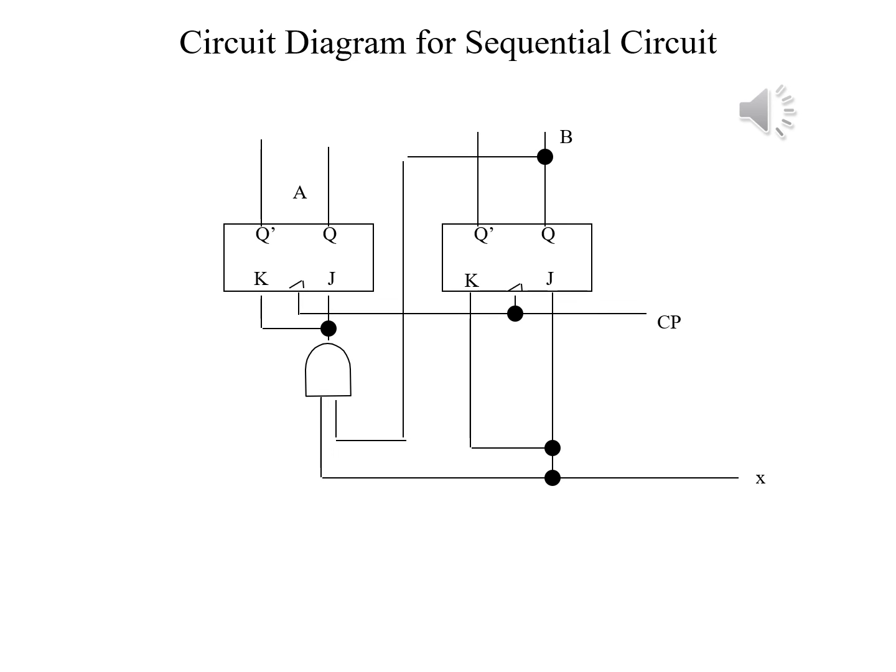Here we see the final circuit. X goes into J, but before that happens, it splits off twice. One to go into an AND gate that B also goes into, and secondly, it goes into KB. The result of the AND gate, which has BX, will go into both J and K for flip-flop A. And this is the completed circuit.